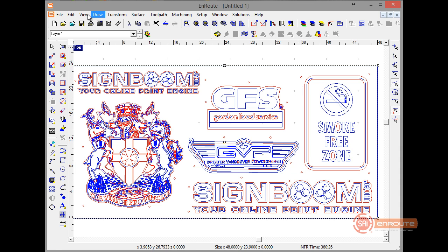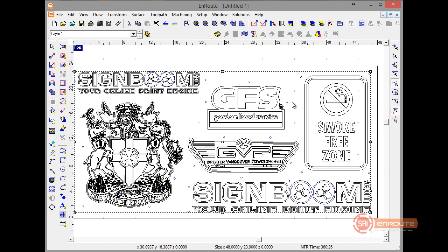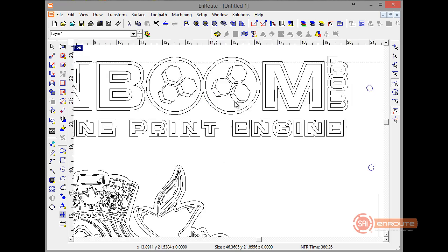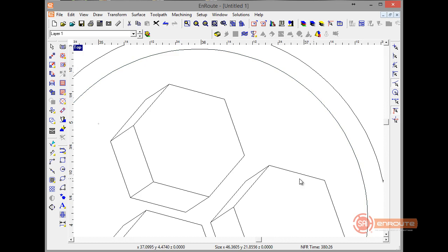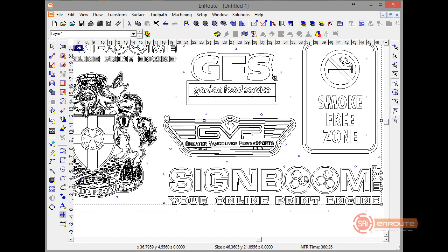And then we're going to go through here and we're going to edit our selection to be just circles. And in addition to our fiducials, there's a couple other objects here that are showing up as circles. So I'm going to hit the control button as I zoom in on these to deselect them. And I'm actually not going to do anything with these, so you could just not have these as part of your output if you want. But I'm going to take all these, and for now I'm just going to group them. I'm going to get rid of this little image I see here that doesn't quite belong.